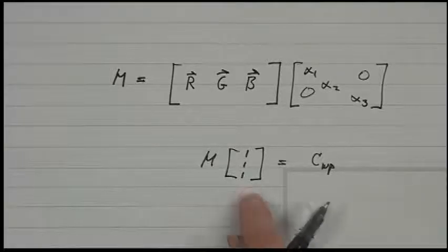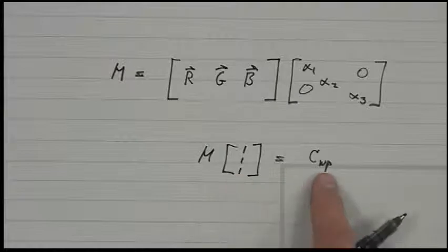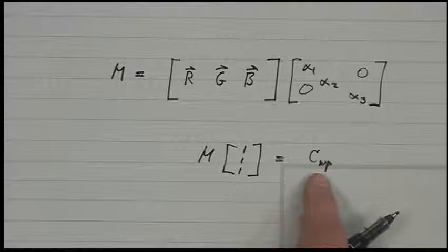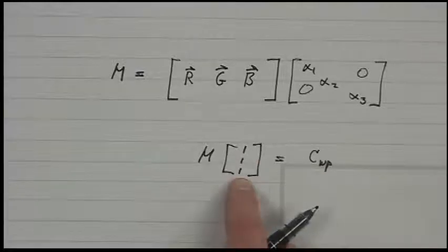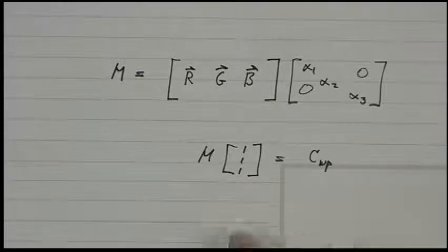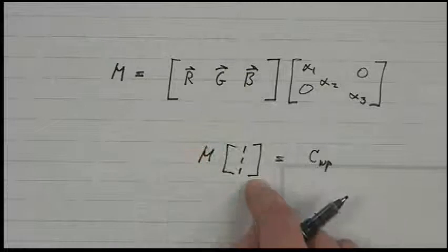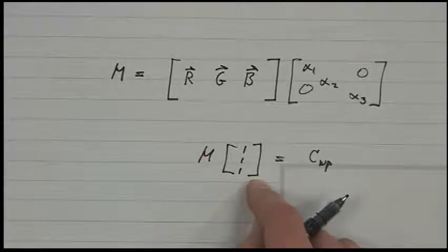And this is getting back to my original point. This is distinct from two other things. The white point, as I said, really has at least three different meanings in my view. One is that it tells you what color you get out when you put an input into the color space of 1, 1, 1. Okay, so it's just a property of the color space you're using. The other is that it's a way of managing, you might say, the color gamut of a device, okay? And the third is it's often a cheap and dirty way of handling color constancy issues in imaging systems, okay?